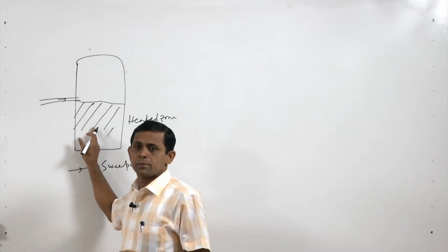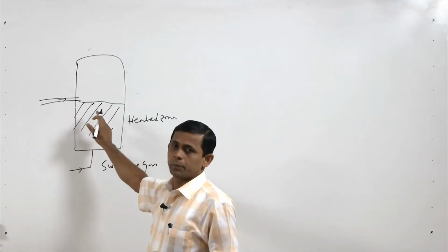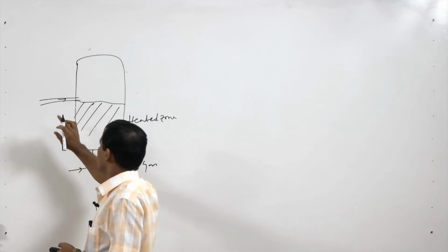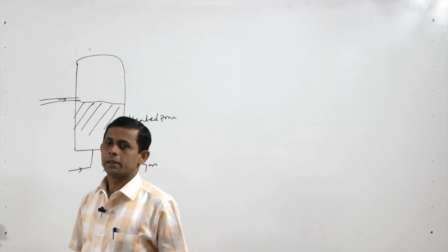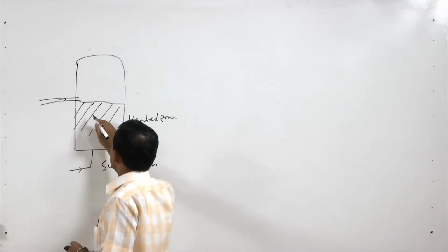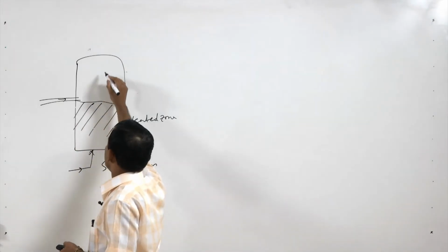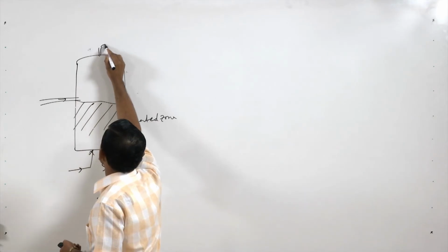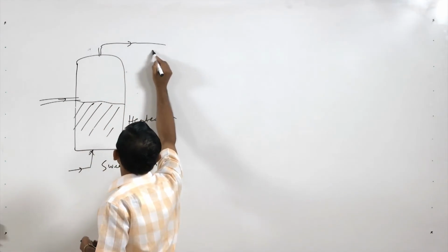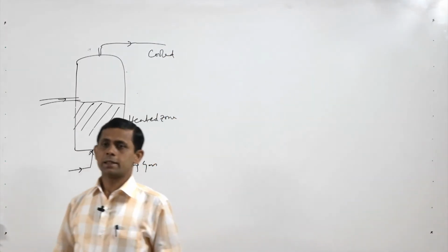As the temperature is maintained here, biomass and waste come here, so pyrolysis will take place, but here the diameter of the particles may be bigger, with no limitation on the diameter of the particles. When it comes in this hot gas, vapors will be created through pyrolysis and go off, and further they will be cooled and we will get bio oil and the gases.